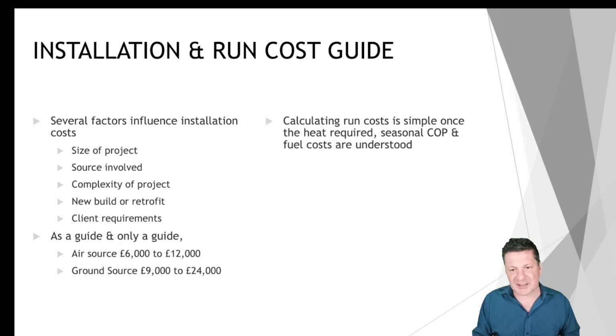On the run cost side, calculated run cost is actually pretty straightforward once you've got the seasonal COP. And again, it must be the seasonal COP, not that rating point COP that you're using to calculate, either estimate or calculate post-installation the run costs.